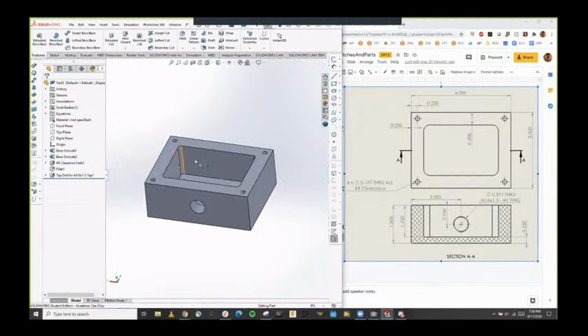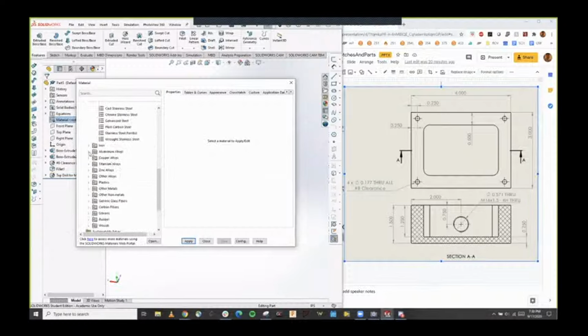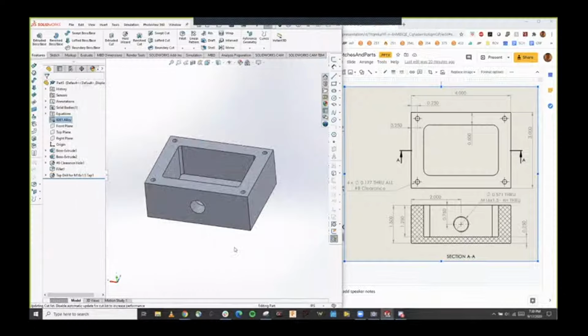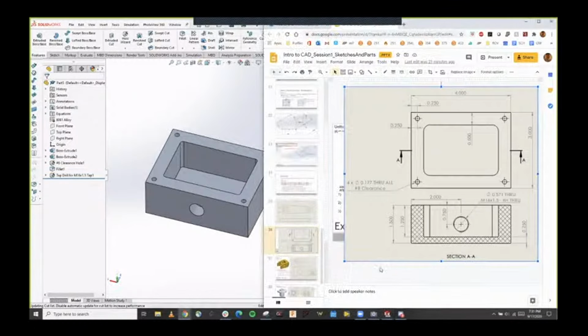The final thing we can do, we go over this more in detail on the 3rd CAD session day, but if you wanted to apply a material, you could go over to the material manager, and for FEA, you need to determine what material is best for your part. So usually on the ROV team, we use 6061 aluminum, which sets it to particular properties that we could run FEA on, and it changes the color just a little bit to help be more representative of what we actually work with.